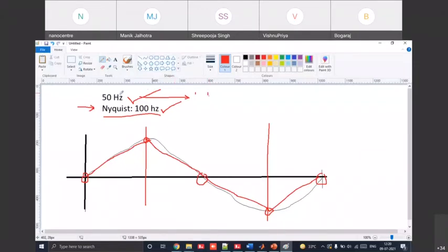So at least as a rule of thumb, the switching frequency which we need to take should be roughly around 5000 hertz in order to perfectly get our simulation answers, depending on the highest switching frequency which we have in the model. If we have 50 hertz, then choose the switching sampling frequency to be 5000 hertz.